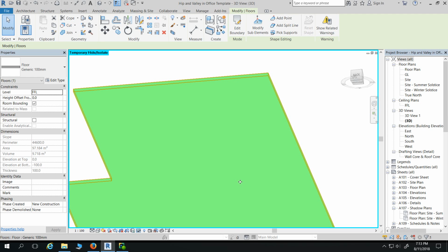This can be really good if you just want to look at individual things in a model. In the final task we'll do in the course, it will tell you to attach walls to roof, which I've just told you not to do. In this instance, it's okay. In 2D, you're building a 3D model, do it in 3D. I tend to always do this for adding slab edge, because I just want to add it to my slab. It can get a bit confusing when there's walls and things like that in the way.